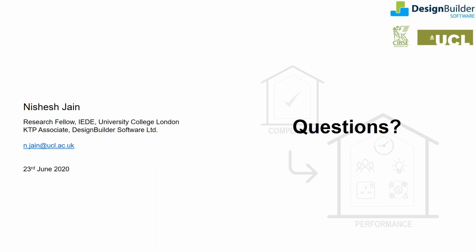Okay, that's good. And a similar line of questioning, just to clarify, I assume that loads such as lifts and escalators were calculated outside of the DSM and would require manual intervention. Yes, when you do a TM54 analysis and start repurposing your model, you need to add those loads in the model because by default they are not included, and ideally you would want to revise the default loads as well.